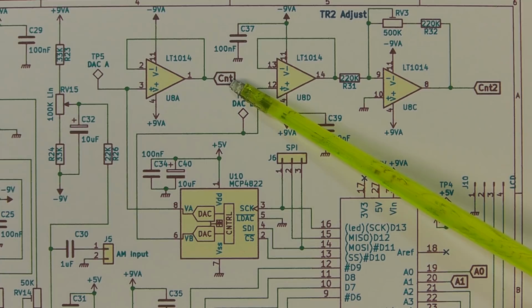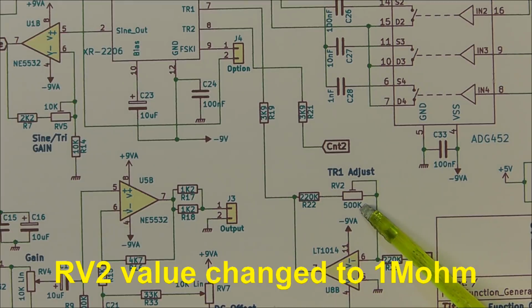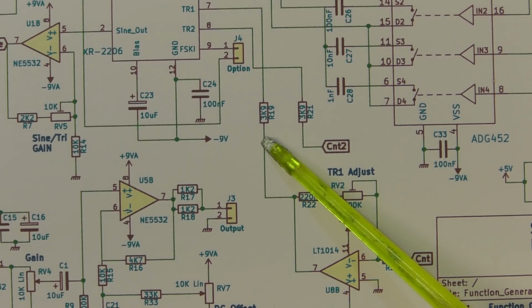So let's have a look at the other part of the circuit where we take that signal to control the timing resistor. The output from the buffer, which is the DAC signal, is now going to this inverting amplifier here, and again we've got some degree of control of that with RV2 to set the maximum voltage swing on the output, which will be a negative voltage. But remember, we wanted something around minus 5.8 volts in our project today, and that voltage is then fed to the end of the timing resistor.